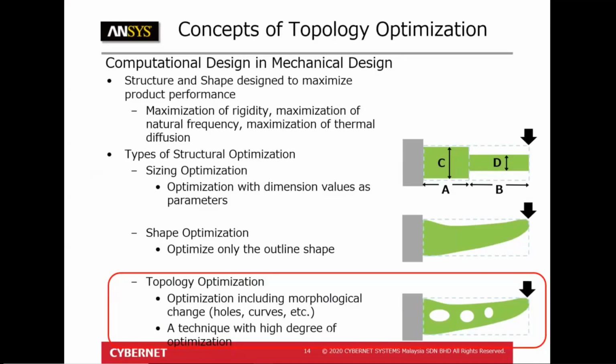Topology optimization differs from shape optimization and sizing optimization in the sense that the design can achieve any shape within the design space rather than working with a predefined configuration. The one thing that needs to be considered when it comes to topology optimization is the feasibility or usability of the optimized shape, because some of the optimization outcomes may be difficult to manufacture conventionally. But like I mentioned before, the growth of 3D printing technology does help in dealing with these kinds of difficulties.